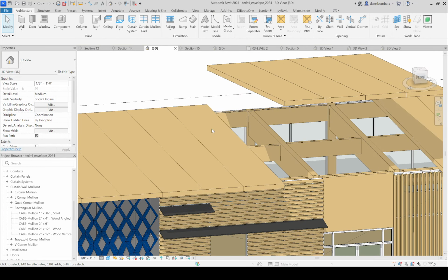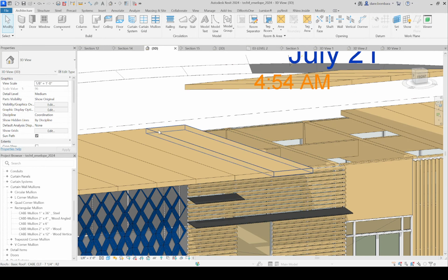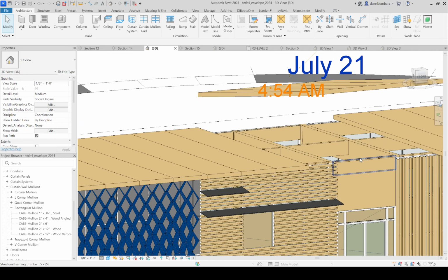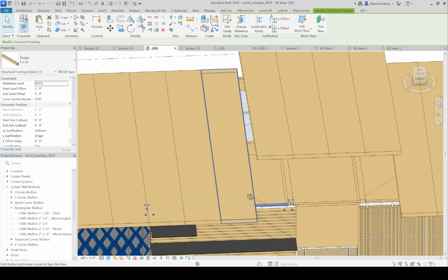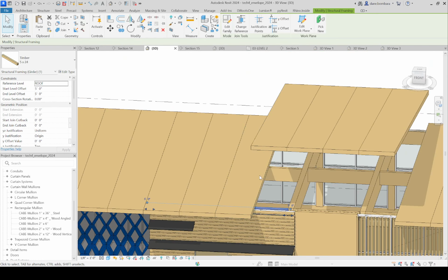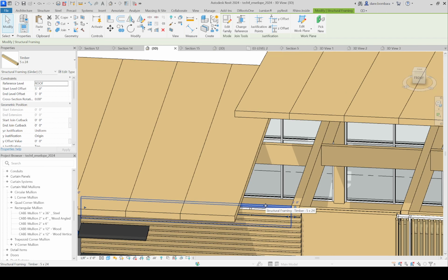And then to create the clerestory, I have to bring my columns up too, because now my beam is down here, just structurally speaking. I need to have either another column that posts off of this beam and comes up and grabs another beam up here, which would likely make this beam heavier, or a deeper beam.